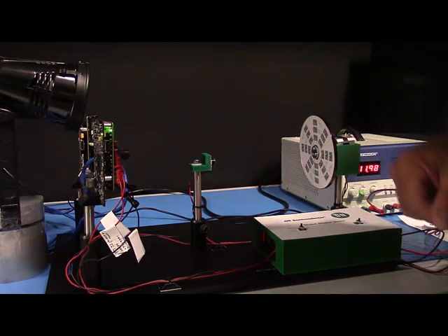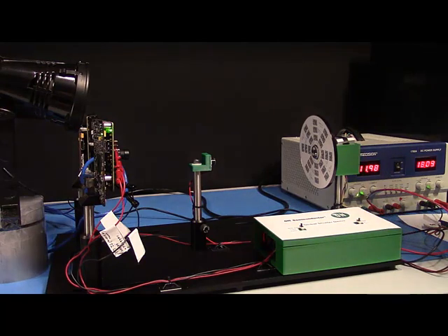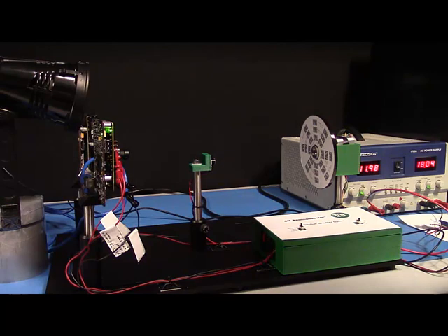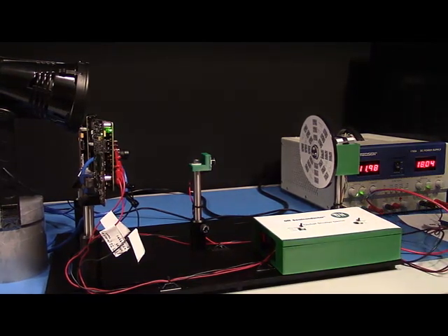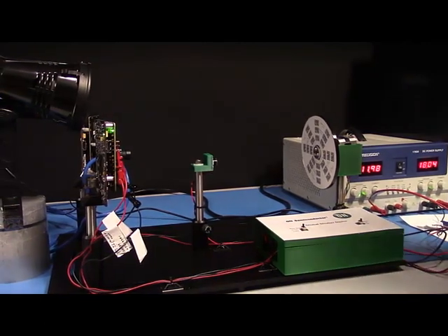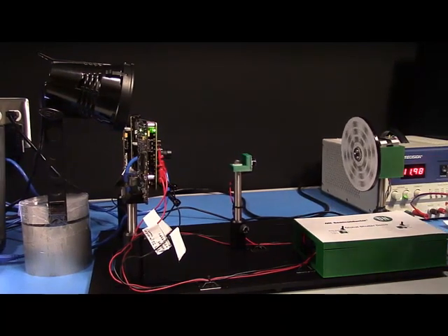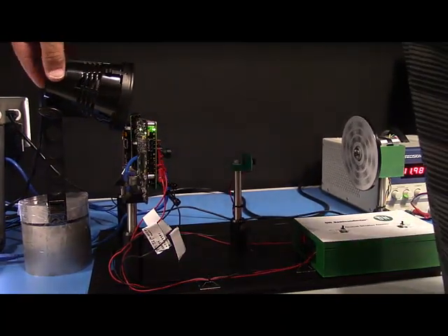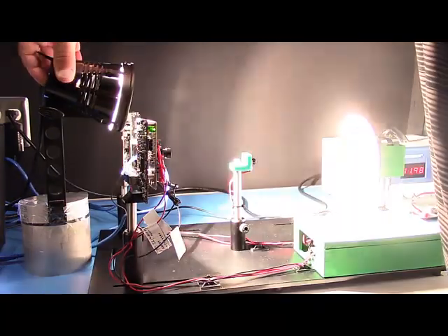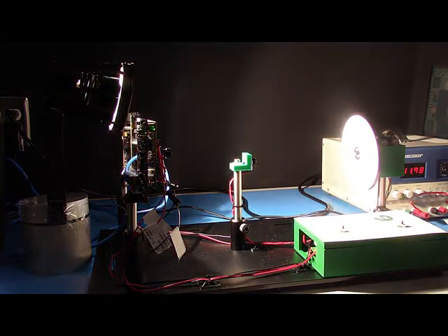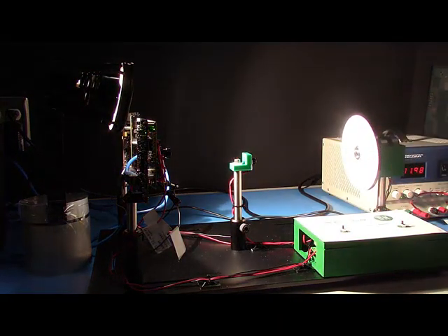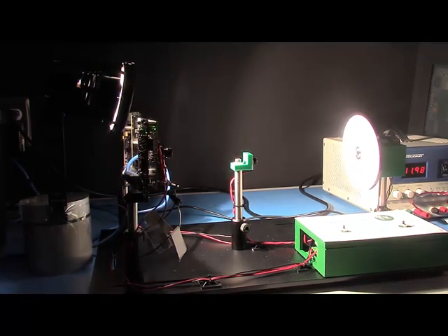Both sensors are running at 100 microsecond exposure time with balanced gains. The target is a set of barcodes like you would see in a shipping warehouse or at your local retail store for checkout. The tangential speed of the target is approximately 125 inches per second for the outer barcodes. The barcodes closest to the center are running about 50 inches per second. Both sensors will have synchronized triggers aligning them to the rotation of the motor. The light source is DC and is supplying approximately 13,000 lux off the face of the target.